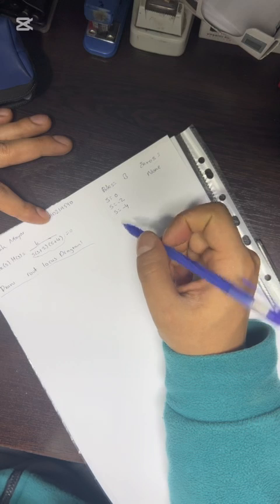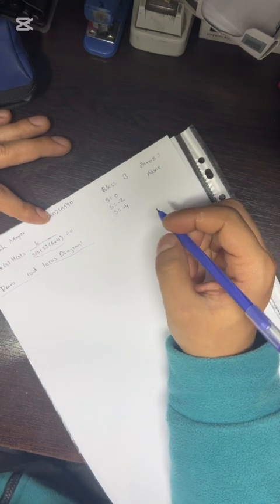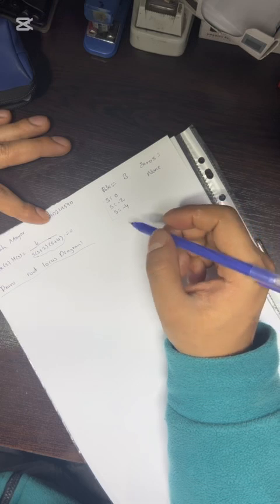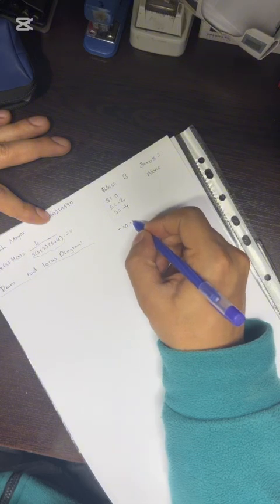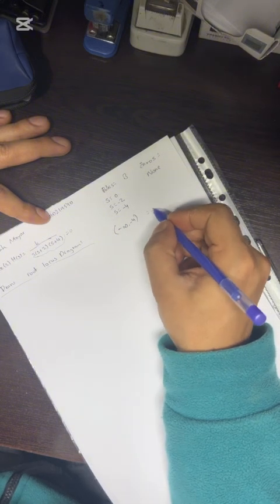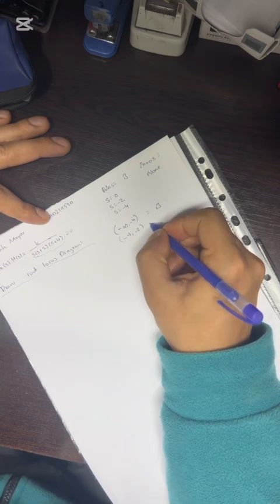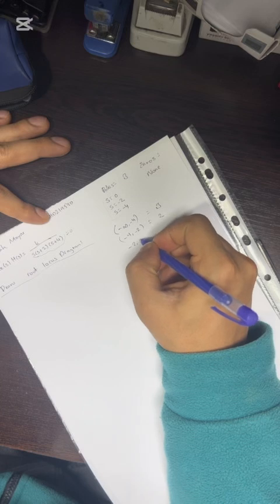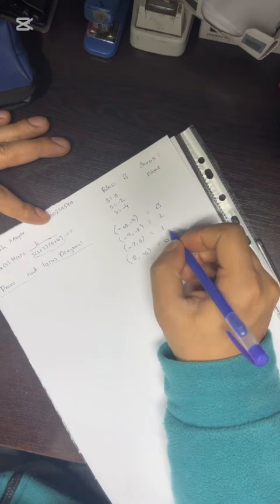Now at first we have to find where the number of poles plus zeros to the right is odd, so we will take those. For example, from -infinity to -4, this is 3. Between -4 and -2, the count is 2, between -2 and 0 it is 1, and from 0 to infinity it is 0.